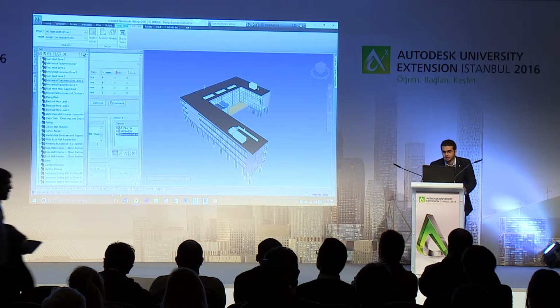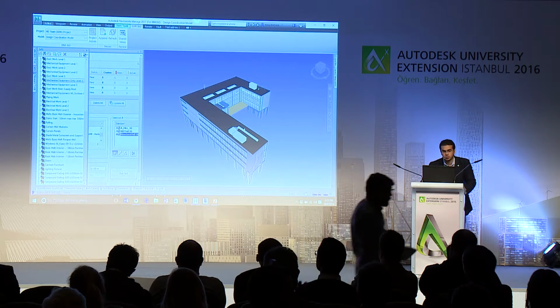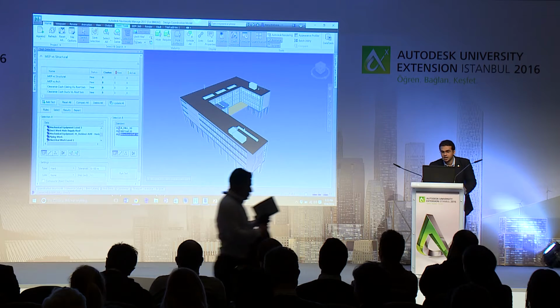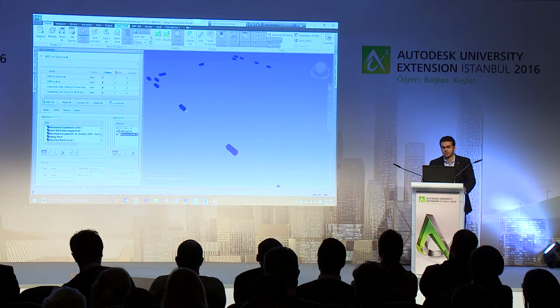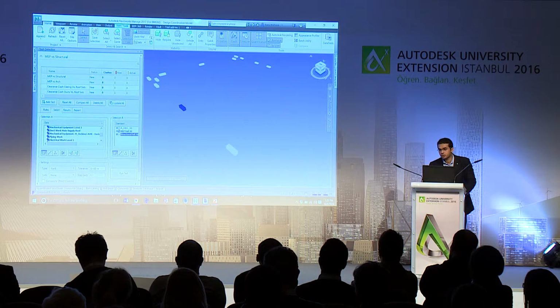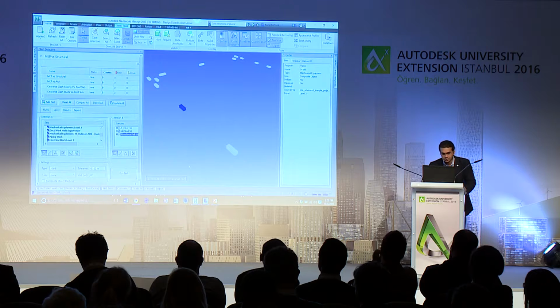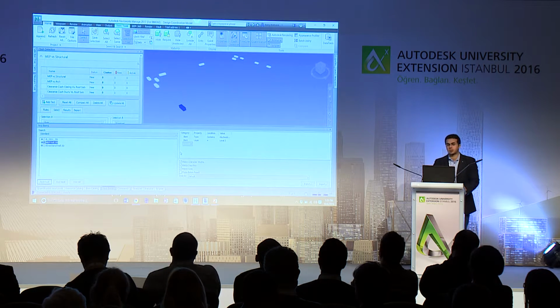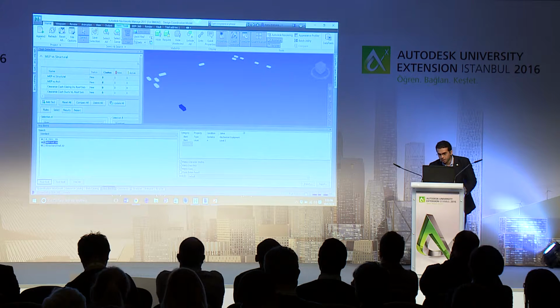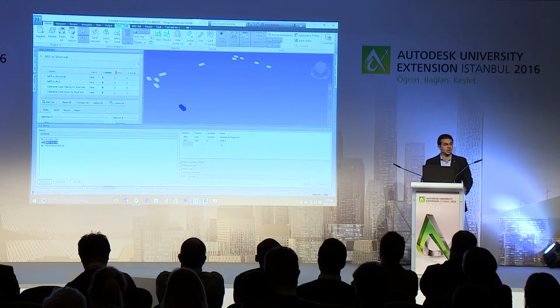Mechanical equipment only level 3. If I go to my home view and say hide unselected, only mechanical equipment that exists in my third floor will be selected. How does this happen? By searching and filtering certain information inside my model. Here I'm looking at my mechanical equipment that resides in my level 3.